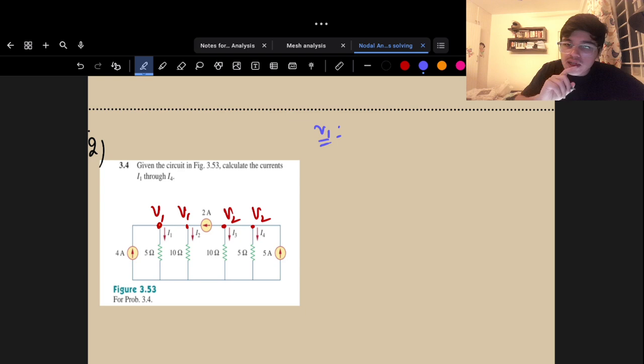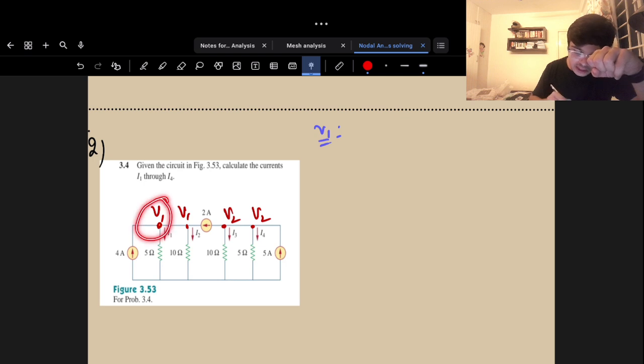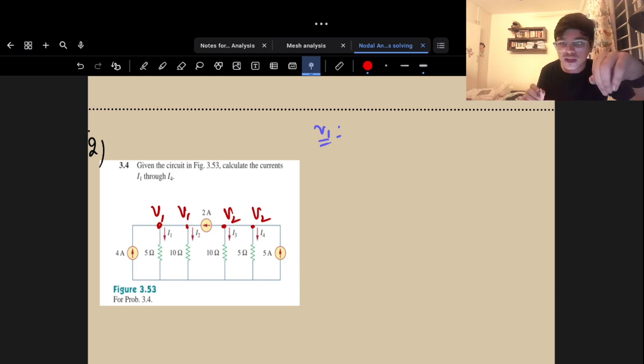Now let's understand the theorem of KCL first. Let me explain the theorem of KCL to you. What KCL exactly says is that the net current entering a particular node is the same as the net current leaving the particular node. It places no physical restraint on what the node is supposed to be. If you look at this question here, physically these two may seem like they are not the same, but from an electrical point of view, these two nodes are exactly the same because they are at constant potential.